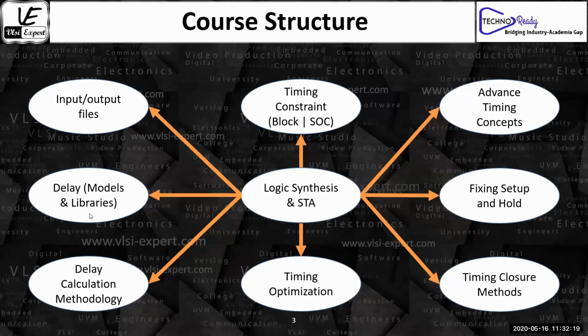Delay models and the delay libraries. Yes, this is the fundamental. This is the root of timing. If you don't know what the delay models are, what the different types of delays are, and how the tool usually does the calculation, what happens in the back end of the tool is very difficult to understand for the STA part.